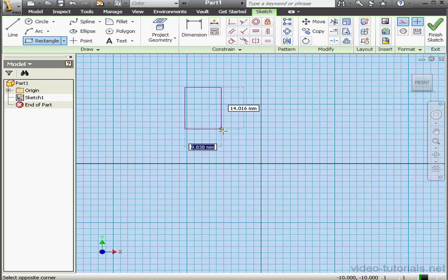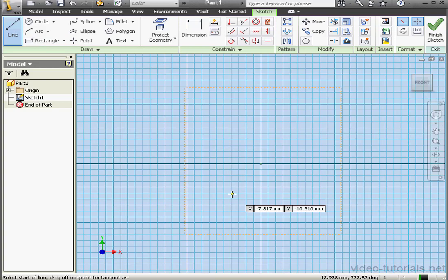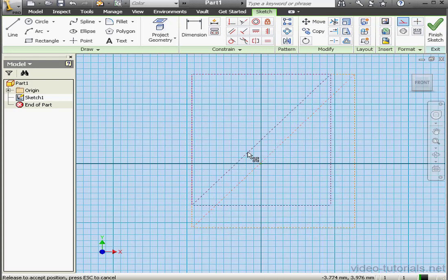Now I'll activate the Rectangle tool, drop it here, and align. Make the beginning of the line coincident to the left corner of the rectangle, coincident to the right top corner of the rectangle. Right-click and done. Now when I resize the rectangle, the line changes size as well.